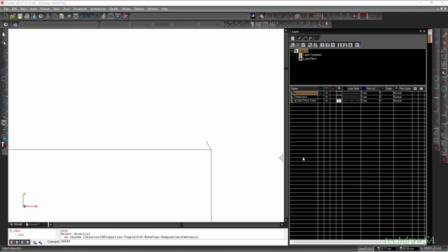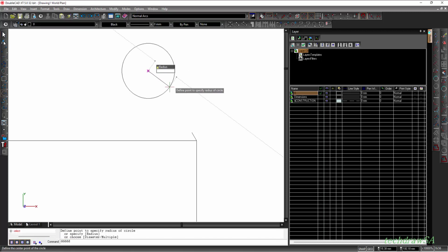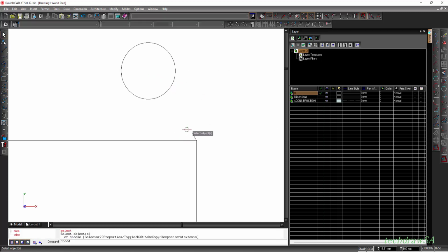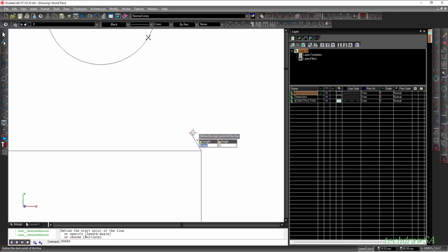Now let's say you want to apply a snap from the end of this line, this end point, to a circle. Let's just quickly draw a circular shape over here, and now you want to snap from that point with a straight line to that circle. So first of all, you go now and select the quadrant point on your snap aperture. You zoom in onto that end of the line because your vertex or endpoint is selected. That will pick up on there.